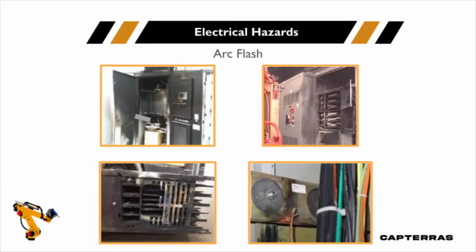On the lower right, you can see this is where a gentleman opened up a piece of switchgear. He opened up some switchgear, and there you can see the ground wire is sitting about an inch away from the busway there. And by the way, this is energized. It's burned off in the past, and he's fortunately in a full arc flash suit.